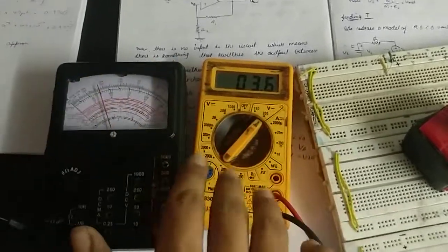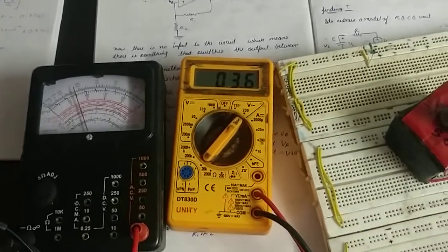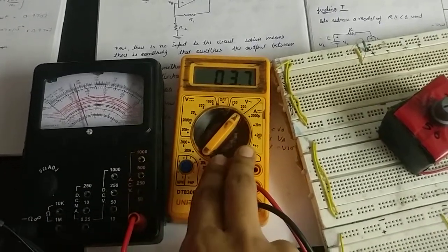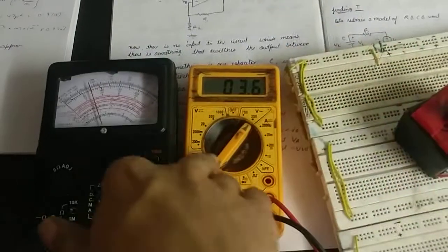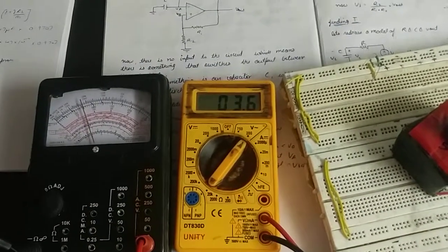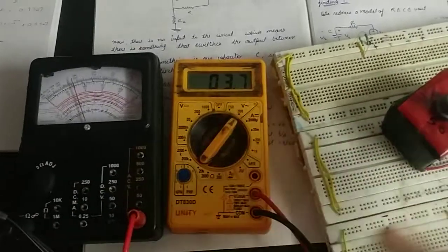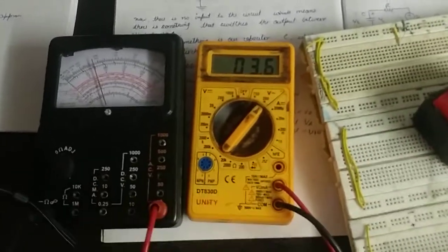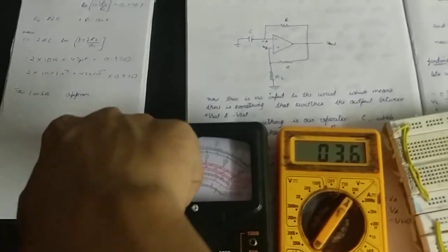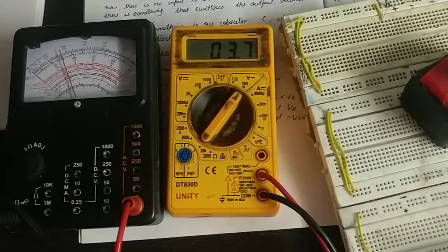This is not the thing that I wanted to show you, because since I'm talking about oscillation, it should oscillate. And as you know, in AC signals, when the frequency is high, the meter actually rounds off the points and shows you the average voltage, and that depends upon how accurate a meter is. Most of the meters are tuned for frequencies nearly equal to 60 hertz. So this frequency is too high compared to 60 hertz, because I'm using a really low value capacitor. So what happens if I switch it to 47 microfarad, because the calculations I have done here are for a 47 microfarad capacitor that gave me 1 second of time period.